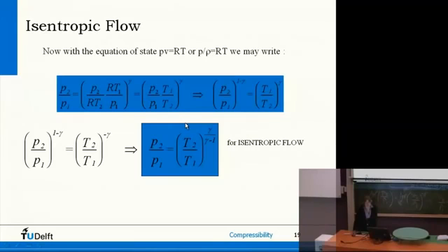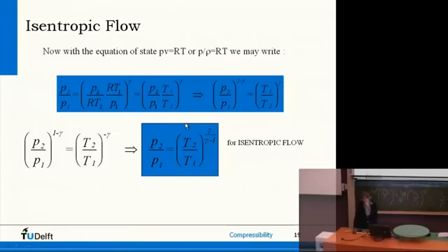So please, I still have gamma. So what I do, I divide both sides by P2 over P1 to the power gamma. Dividing the right-hand side by P2 over P1 to the power gamma, this one drops out. Dividing this side by P2 over P1 to the power gamma, I get not 1, but then the minus gamma here. So the relation between pressure and temperature is this one. P2 over P1, 1 minus gamma is equal to T1 over T2 to the power gamma.